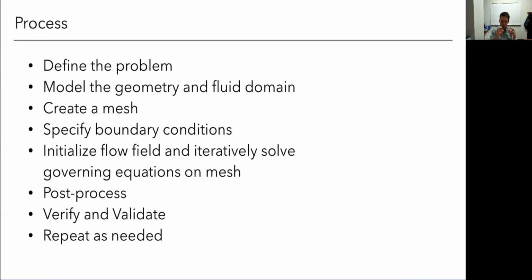I've already gotten kind of close and I can refine. This is also, by the way, a good way to do that mesh refinement study. Since I should do that anyway, and you should always do that, I can do this to kind of iteratively refine towards a solution, and it isn't too costly because I've already got a decent solution. So when I refine, running it again is pretty quick.